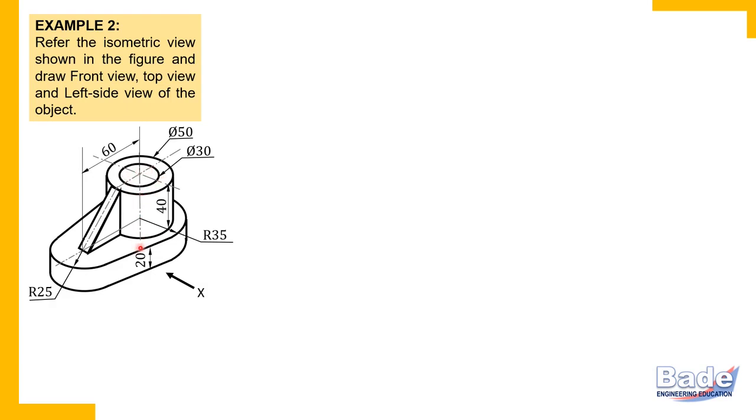So it is not just 40 millimeters long, it is extended in this plate also, so that this hole has opening at the base of the base plate. Listen. If this hole is not a through hole, and if this hole has certain depth, then this is how that depth is mentioned in the dimension. Phi 30, that is diameter 30 and 30 deep, it means this hole is 30 millimeter deep and not a through hole. So in 40 millimeters high cylinder, this hole is bored or drilled up to 30 millimeters only.